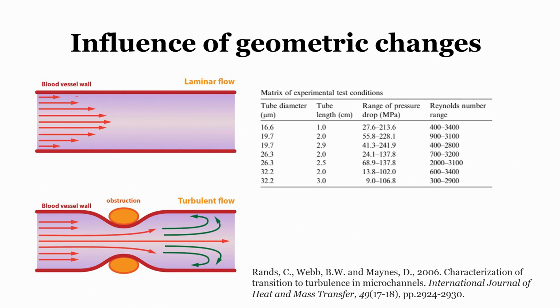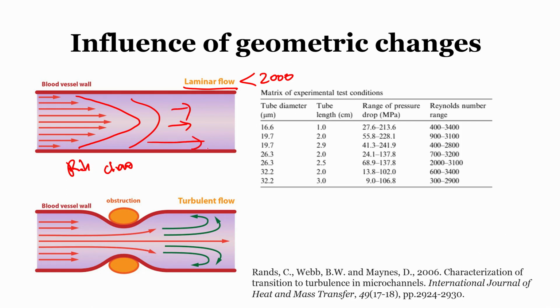This is how the fluid flows. The fluid flows something like this, and this is called a laminar flow, where the Reynolds number would be less than 2000. So, what happens when the fluid is flowing in a laminar manner? The resistance offered would be low. There is no chaotic movement in the channel. All of them throughout the length tend to move in a similar fashion. They do not crisscross, so the fluid flows from one end to the other end. This is why it is laminar flow, and when it is turbulent,